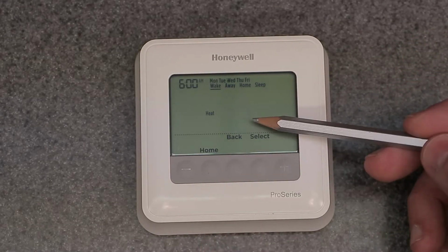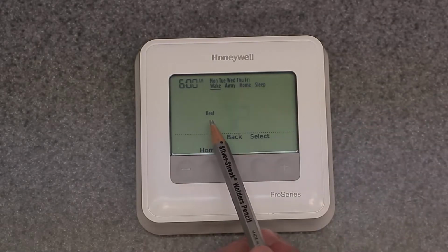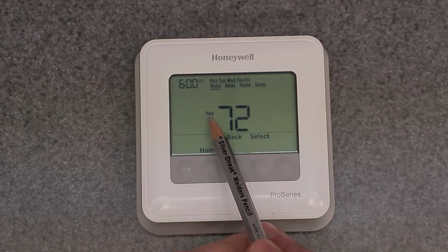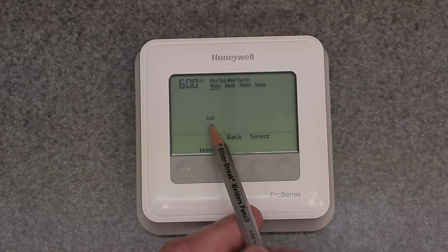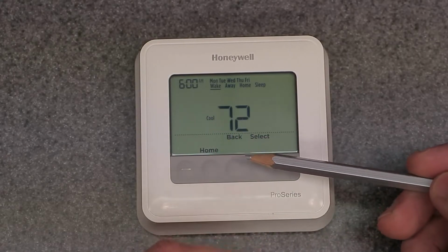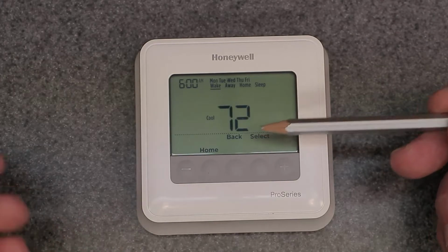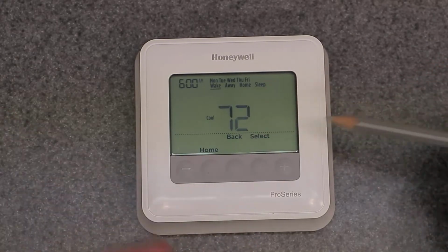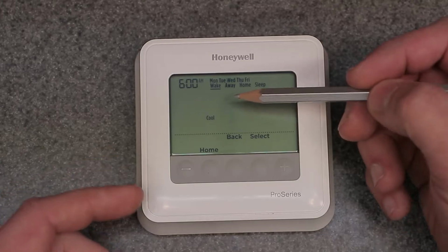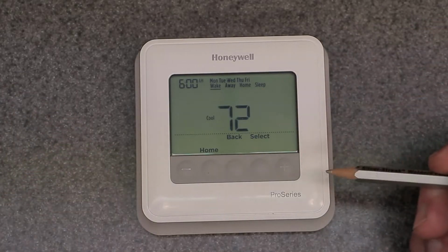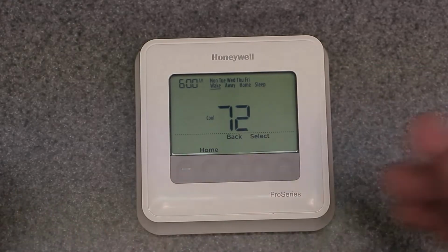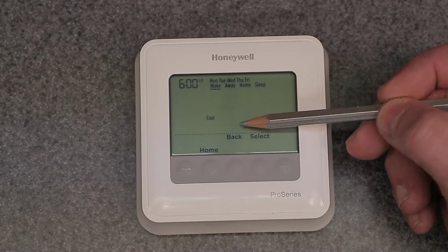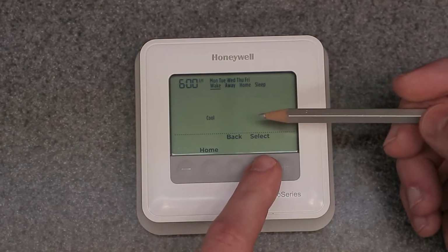So this is going to be your set point for the heating cycle because it shows that it's in the heating mode right there. Hit it one more time. Then you would go into cooling mode. This would be your set point if you had your cooling on. It's kind of different from other thermostats out there. You have to set your heating and cooling at the same time, which is actually kind of nice because you don't have to go back and do 2 schedules separately. As you can see there, we're just going to leave it on 72 for the sake of the video.